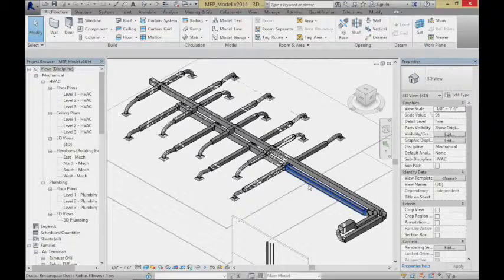Okay. Another strategy that you find used in a lot of slightly older buildings is we'll duct the supply, but we'll have what's called a plenum return. And what's that all about? That's the notion that in the ceiling space over here, I might run the supply ducts. So I've got some sort of supply duct coming through. Everywhere it needs to, it has some sort of drop that goes to a ceiling diffuser. I've got one over here that's coming to a ceiling diffuser over there.